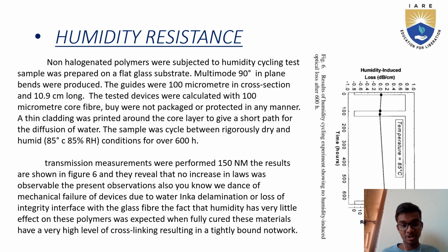There was also no evidence of mechanical failure of devices due to water, such as delamination or loss of integrity at the interface with the glass fiber. That humidity had very little effect on these polymers was expected when fully cured. These materials have a high level of cross-linking, resulting in a tightly bound network.